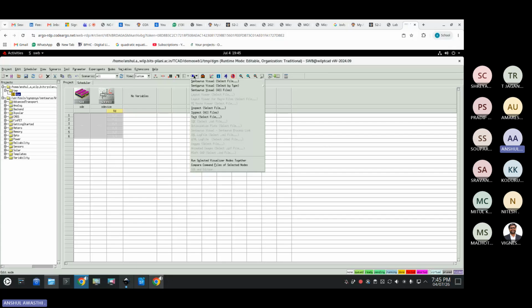With respect to your device, the value of current will change. For example, MOSFET has some current, and your device has some more current than MOSFET. Then it will perform better with respect to MOSFET. So you can import your device and compare with the GPDK 45 nanometer case there in the Cadence. Whatever device you have constructed, double gate MOSFET or any device, you can import it in the Cadence using Verilog code, make an inverter with your device and an inverter with the normal MOSFET, and compare the performance. Yes.